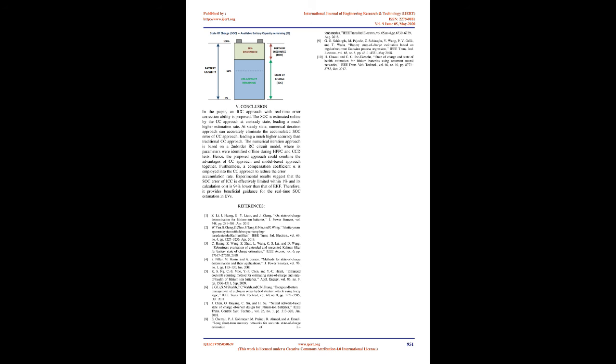Furthermore, a compensation coefficient is employed in the CC approach to reduce the error accumulation rate. Experimental results suggest that the SOC error of ICC is effectively limited within 1% and its calculation cost is 94% lower than that of EKF. Therefore, it provides beneficial guidance for the real-time SOC estimation in EVs.